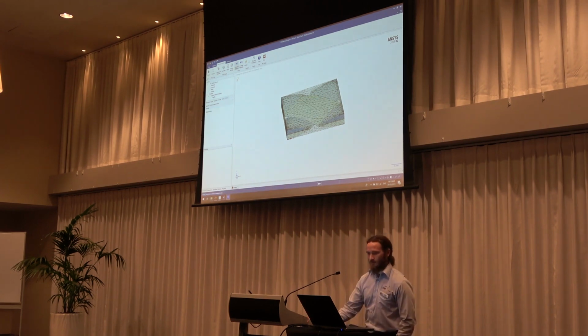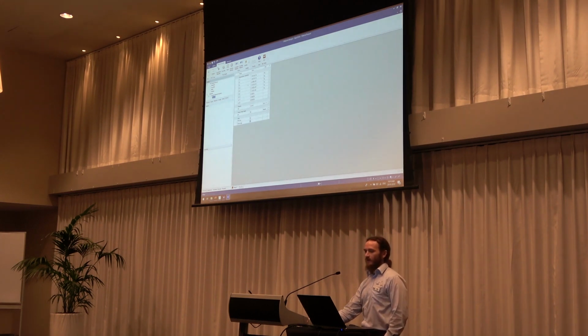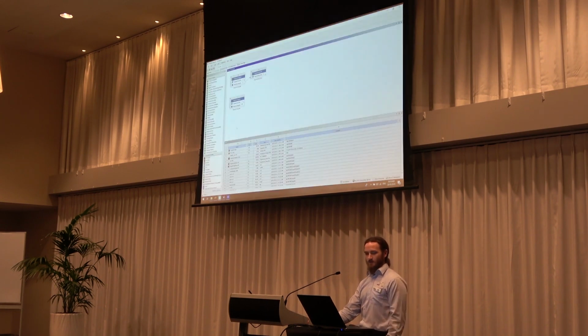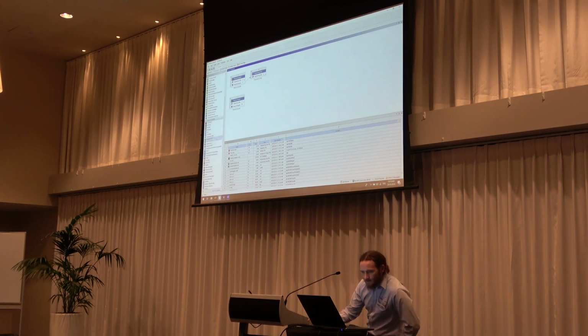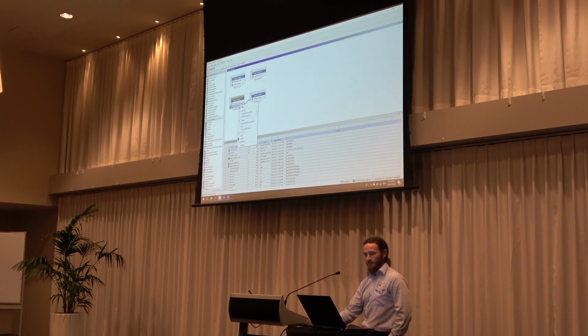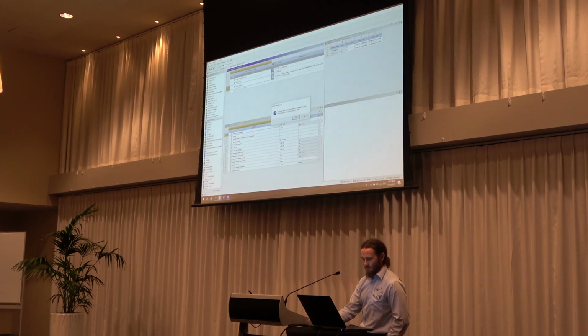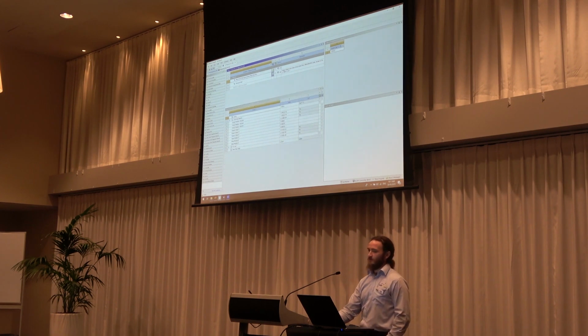So that's all done, and we look at our results, and we have our Young's moduli in the 1, 2, and 3 direction, shear moduli, and the Poisson's ratios. And then I can just go into engineering data, which is here, drag that in there, update all of this, and then yes. And there's our new material property that we've just calculated, and you can use that in ACP or whatever you like.